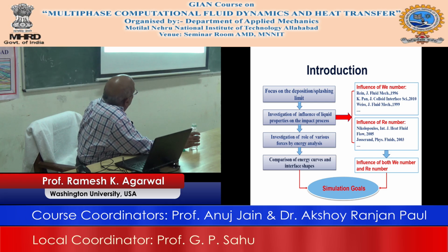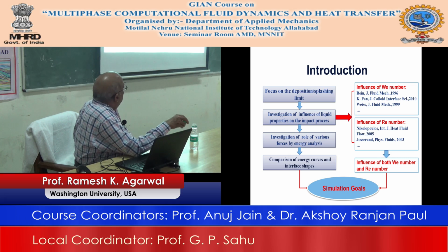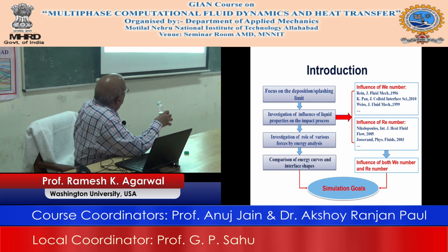and then there is experimental data available. So those of you who have listened to me, not only in this particular course, but any time before, know that I never believed a CFD unless you have validated it. Because there are so many quirks there, not only about the mesh independence, not only about the boundary condition, turbulence model, etc., that if something or the other is not done right, then you can get an answer, but it can be quite off. So these are the references that are given from the point of validation.